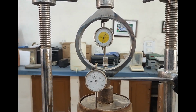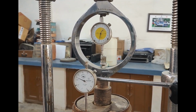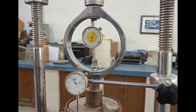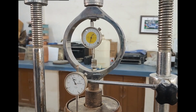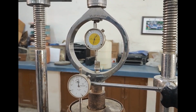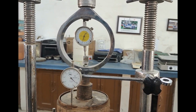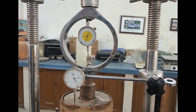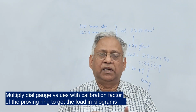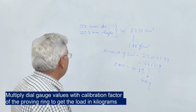And then you determine the load value at different penetration values. Penetration values are 0.5, 1, 1.5, 2, 2.5, 3, 4, 5, 7.5, 10 and 12.5 millimeter. That completes the test. Now you have the load and penetration value. So make a graph between load and penetration.